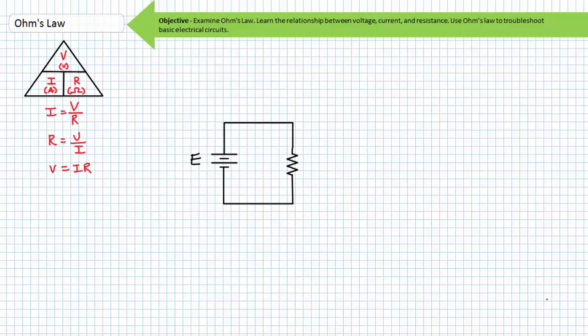Before we attempt some illustrated example problems of Ohm's law, we need to discuss 3 topics, namely the difference between a voltage rise and a voltage drop, and we've got to introduce both polarity markers and subscript notation. These topics might seem a little unnecessary at this point, and even glaringly obvious given such simple circuits. But trust me, this brief orientation to rises versus drops, polarity markers, and subscript notations will make life much easier as we progress into more complicated circuits.